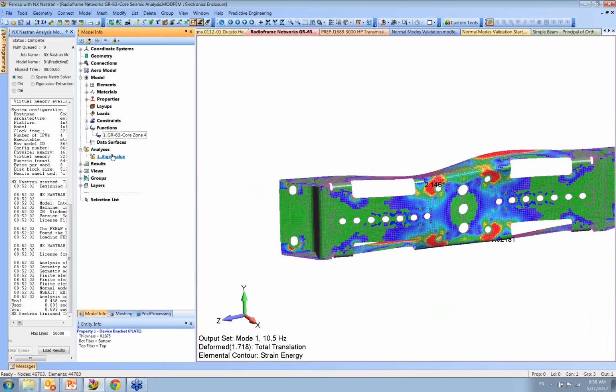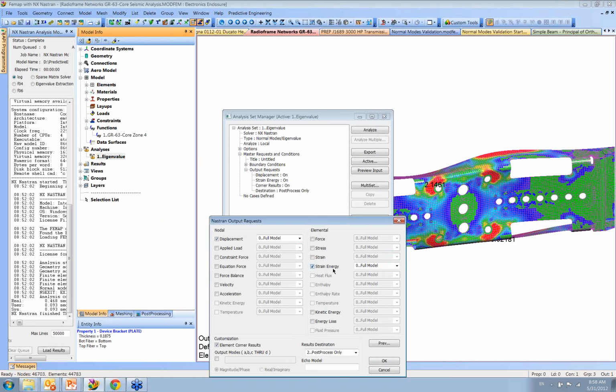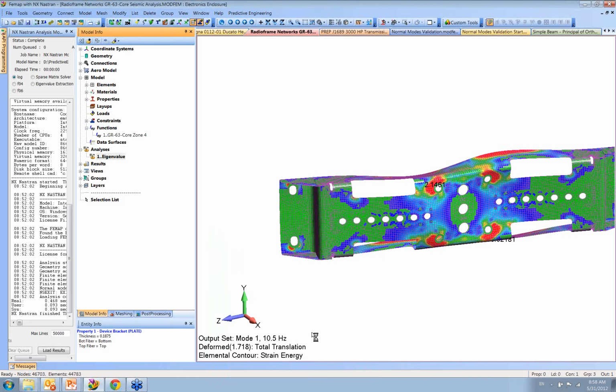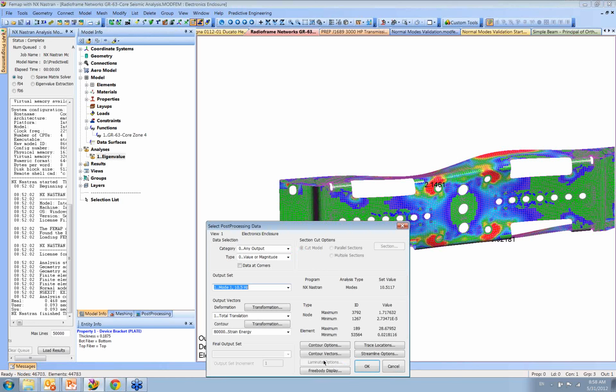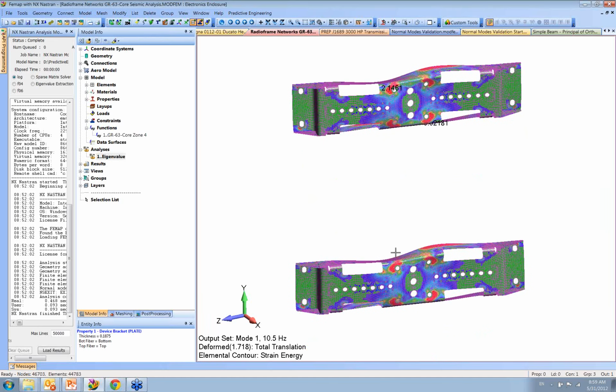So where do you request strain energy? Go down through here, master, output request. Right there. That simple. You just request that it gets dumped out, and you're going to get crazy numbers. The numbers go all over the place. For strain energy, you get 28.67 or 0.02, I have no idea why. The way I treat it is I'm just looking for relative changes, and I don't give any importance to the magnitude because there are no forces. The magnitude doesn't mean anything. It's like the deformed shape.